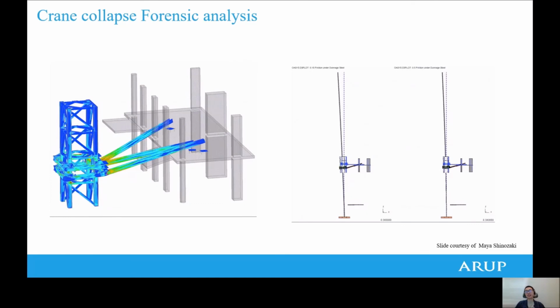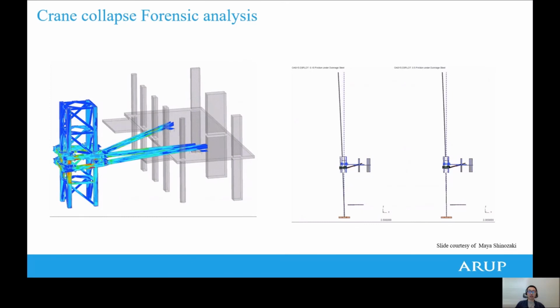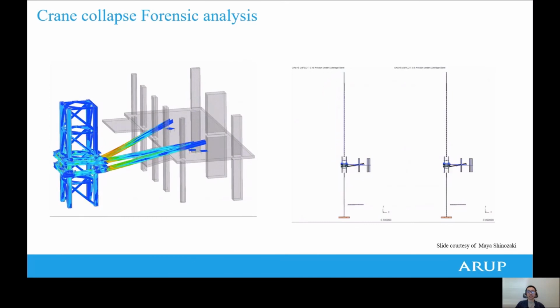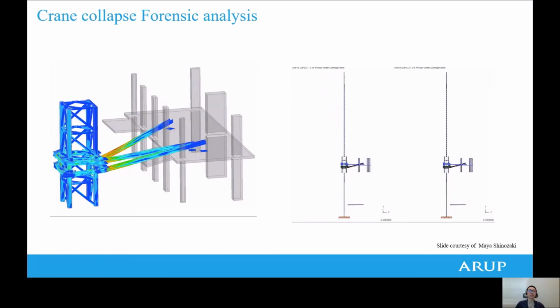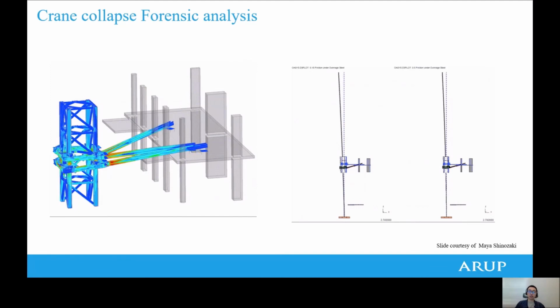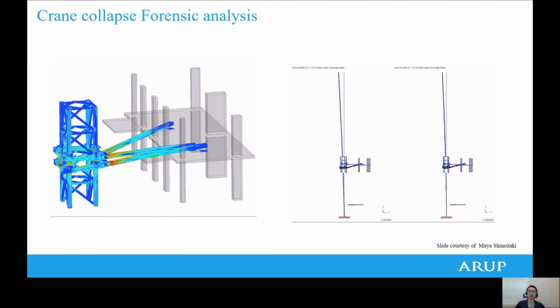The crane tilts a large amount with the total loss of connection with the 9th floor. When a higher friction coefficient is assumed, the tilt is much less. You can see the comparison in this animation. Moreover, a catastrophic collapse is predicted to be avoided. So LS-DYNA modeling in this case was very useful in understanding the complex interaction between different components at varying scales, and it allows us to visualize the failure sequence and understand some of the critical issues which affect the